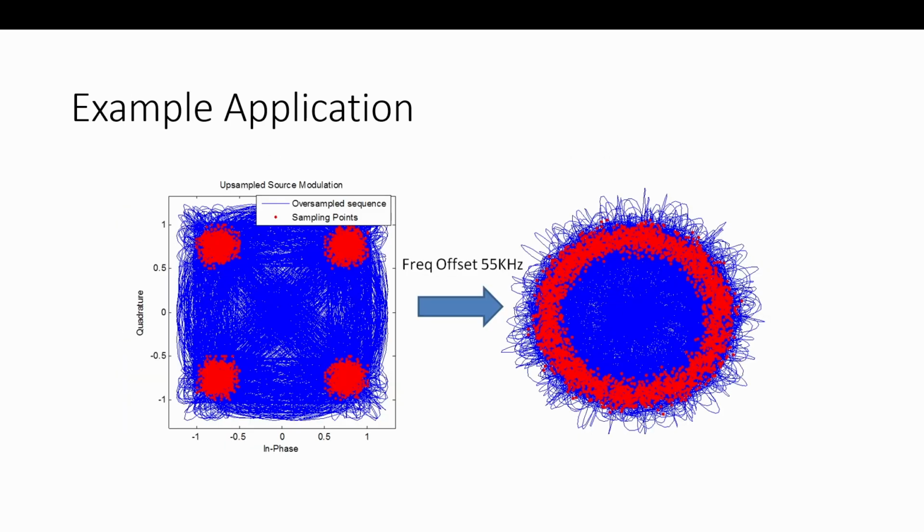So to show you the background of that, there's a simulation I did. So a simulation I did showing, hey, we have, in this case, QPSK. So you're seeing QPSK, and you're seeing all the transitions from symbol to symbol as it changes from one symbol to the next, all the possible transitions that you're seeing at IQ baseband.